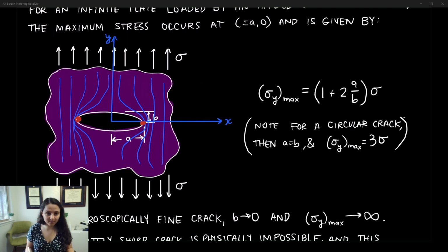Okay, so we're not just talking about the difference in having a cross-sectional area that extends all the way across versus a cross-sectional area where we've taken out some material. Okay, so that's a different concept entirely. Here we're talking about the stress being amplified at the corners because of the discontinuity, because we have a defect, a crack. So in this infinite plate, right, if we take out a little bit of material, it's still close to infinitely wide. This cross-section is still close to infinitely large.